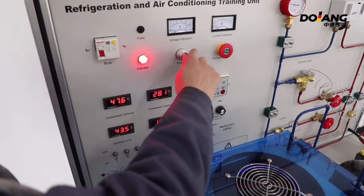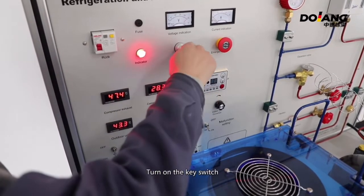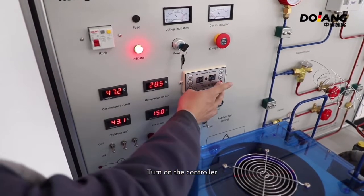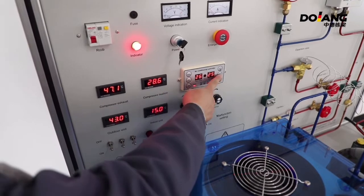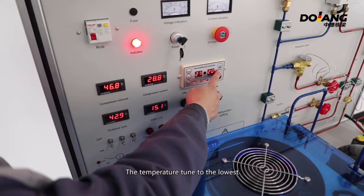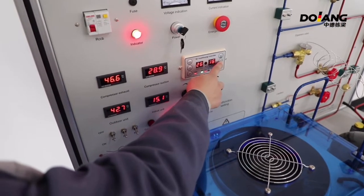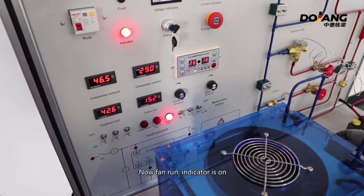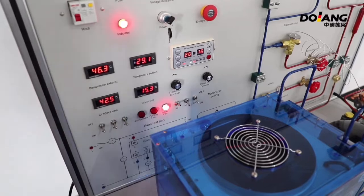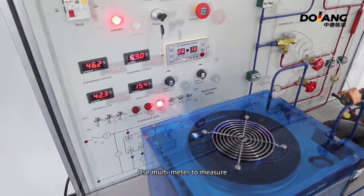Now do the fourth fault experiment. Turn on the circuit breaker. Turn K4 to off. Turn on the key switch. Turn on the controller. Turn mode to cooling state. Turn temperature to the lowest. Now the fan runs and the indicator is on, but the compressor doesn't start. Use a multimeter to measure.